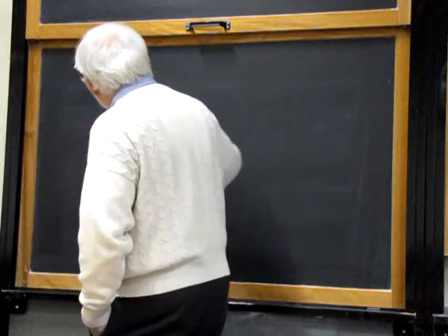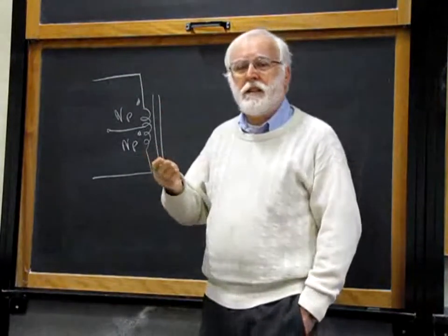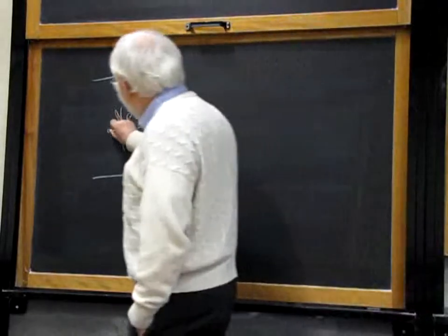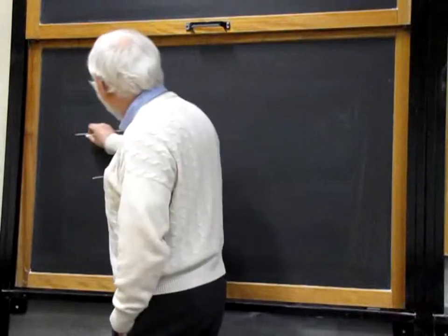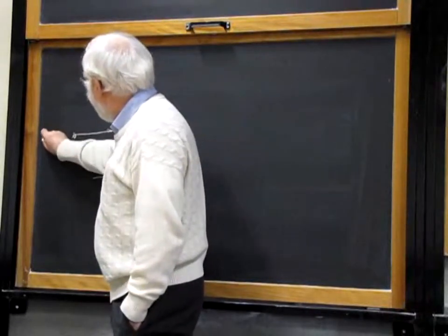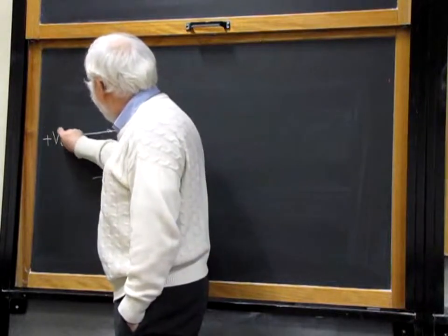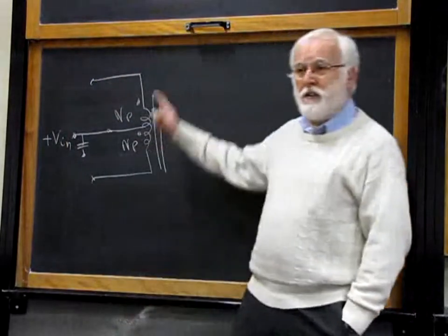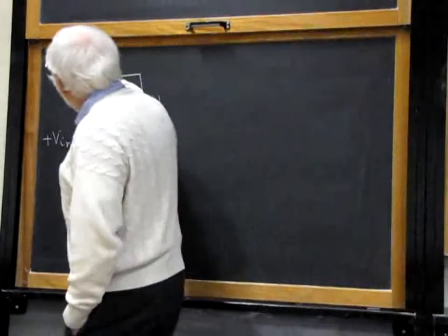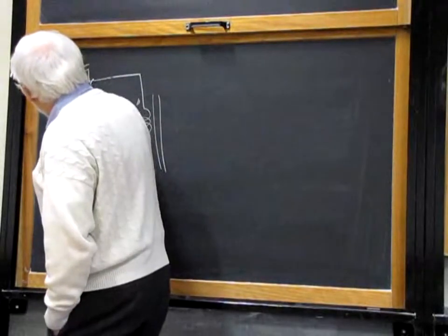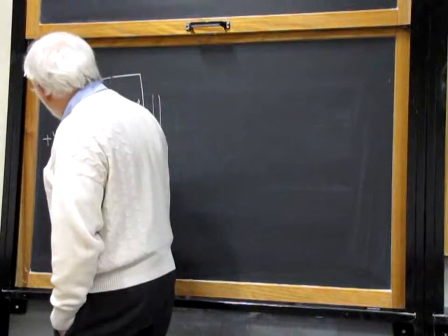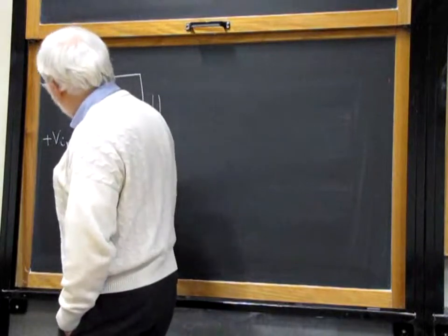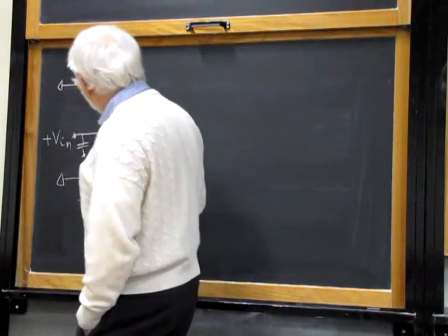And we need to drive the core once with one polarity and the next cycle with a different, opposite polarity. This is obtained by taking the central tap to positive Vin, and the two ends of these two windings are connected to ground with two transistors, S1 and S2, like this.